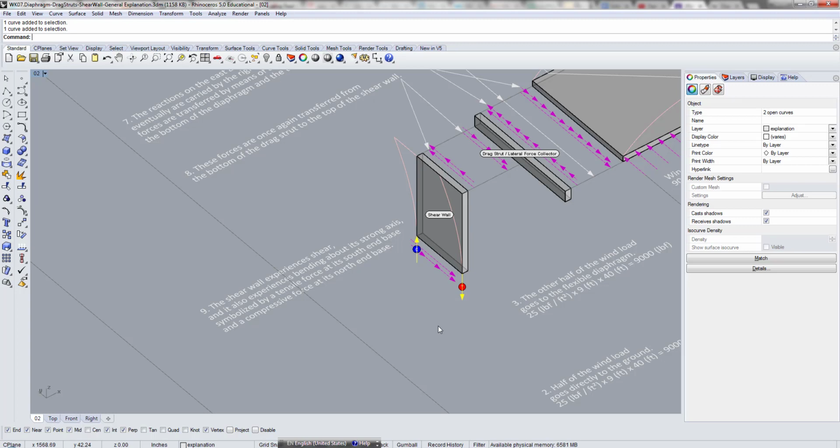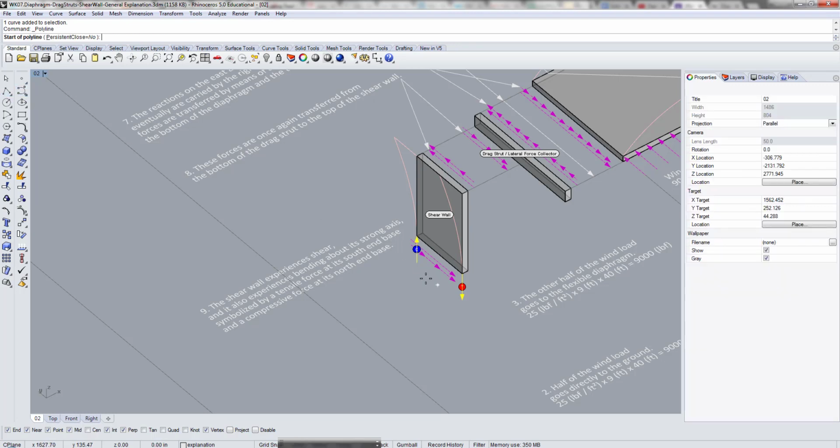right? And if you remember rotation, you remember the term couple, moment of a couple, right? A couple of forces refers to forces of the exact same magnitude and opposite direction, separated by a distance. That's called a couple of forces, and what this does is create a moment.